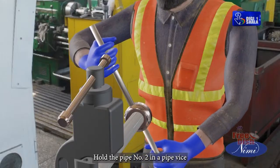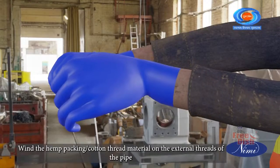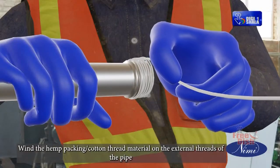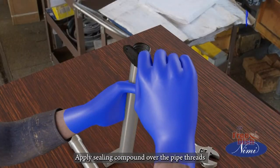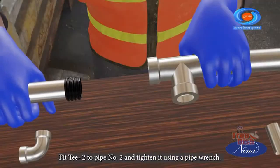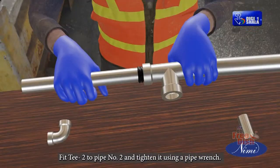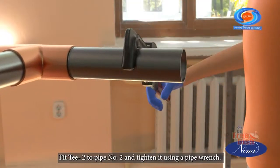Hold pipe number 2 in a pipe vise. Wind the hem packing or cotton thread material on the external threads of the pipe. Apply sealing compound over the pipe threads. Fit T2 to pipe number 2 and tighten it using a pipe wrench.